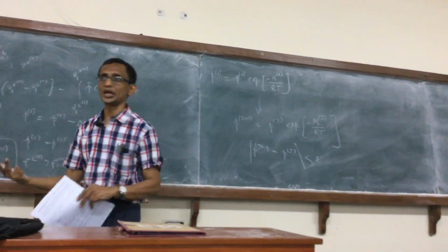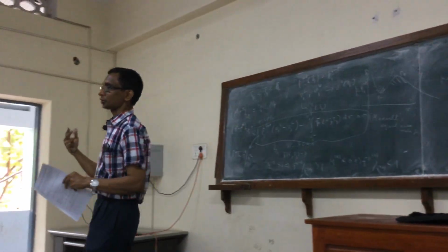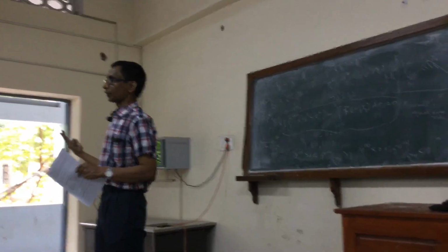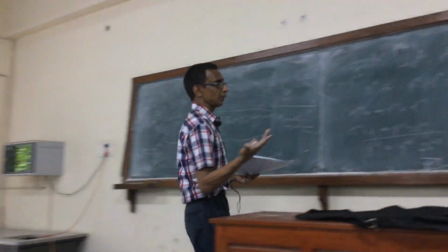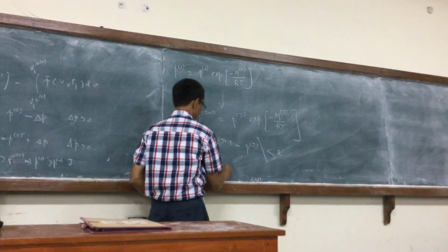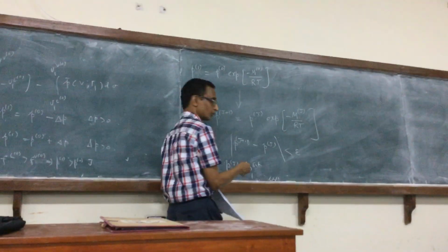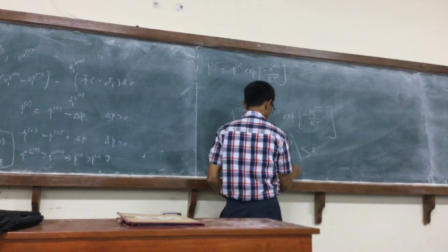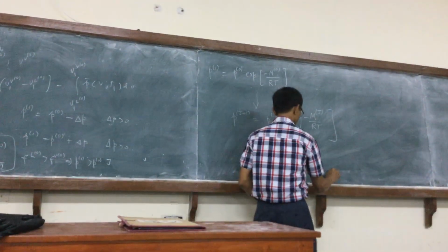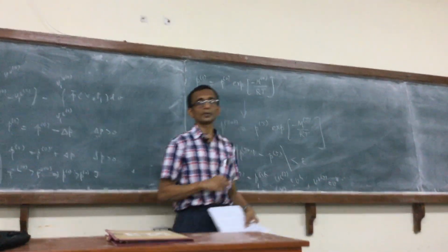So if it doesn't change within a tolerance limit, then we say we have determined the saturation pressure to that accuracy. So we may then take either P J plus 1 or P J, whichever we want. So we can then take P J to be equal to P sat, and then whatever volumes I have found, V L of J becomes V L and V V, and the procedure is complete.